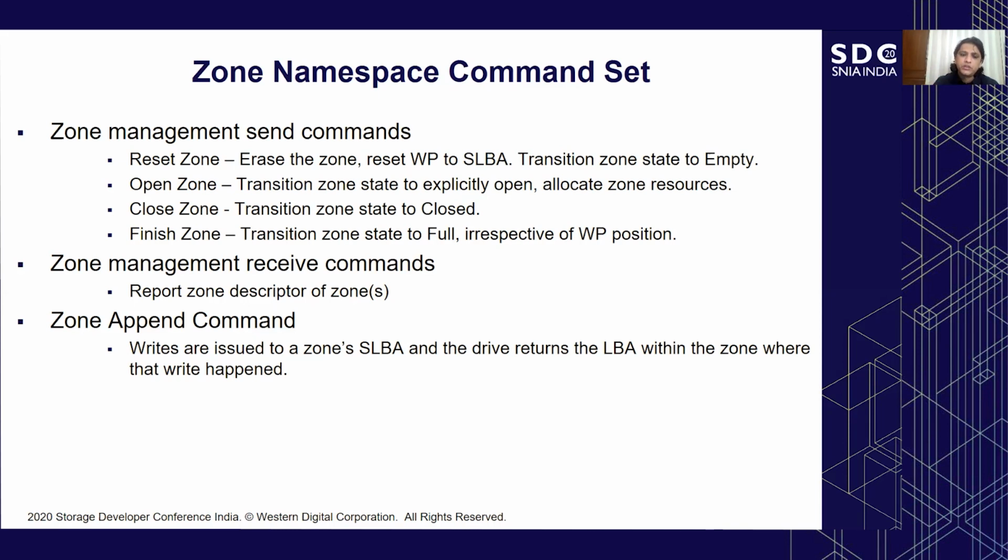However, the user or the application can also move the zone state to full at whatever the write position. Even if it is not full, the user can send a command to transition the zone into the full state. So, zone management receive commands. This is a command to get a report on the zone descriptor of a zone. Zone descriptor is again an attribute of a zone, which basically defines some customizable characteristics that a host wants to maintain.